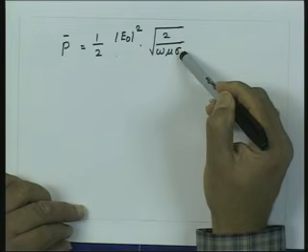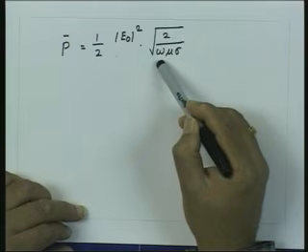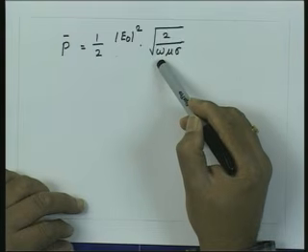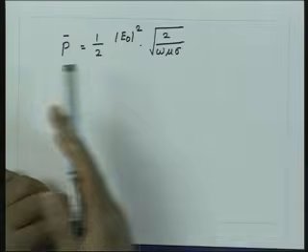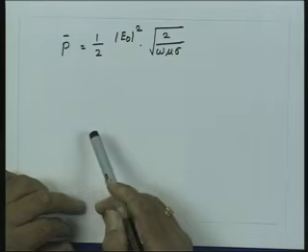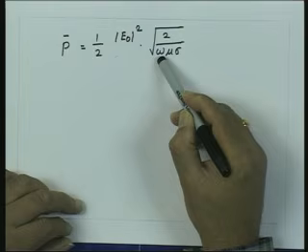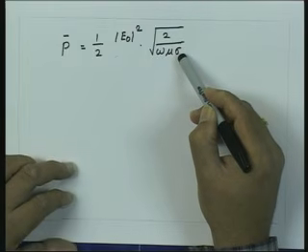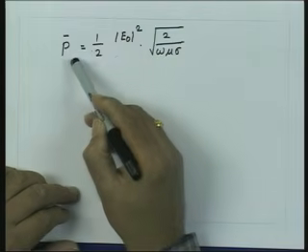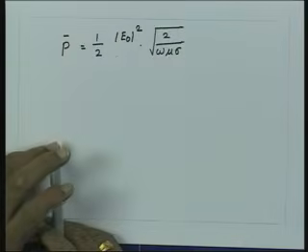That means as the conductivity becomes larger, and the same thing is true for frequency, as the frequency becomes larger, the power flow inside the conductor reduces. And when you go to very high frequency or you go to ideal conductor, which is sigma equal to infinity, then the power will go identically to 0. That means for an ideal conductor, there is no power going inside the conductor. Similarly, when the frequency becomes large, there is no power which is going inside the conductor.